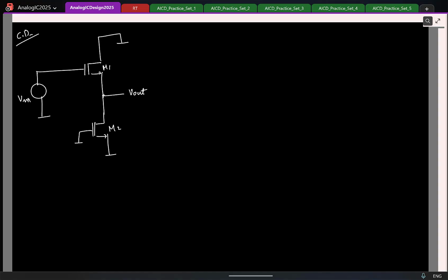So now let's start marking the capacitors. From the gate, again as I told, I have capacitance from the gate to all terminals. What I'll do is lump all the capacitors from the gate to the ground as one single capacitor, call it some C. This capacitor will include the gate to drain capacitance, and the gate to bulk capacitance, which is grounded, by the way. I'm not showing it. I think that's all.